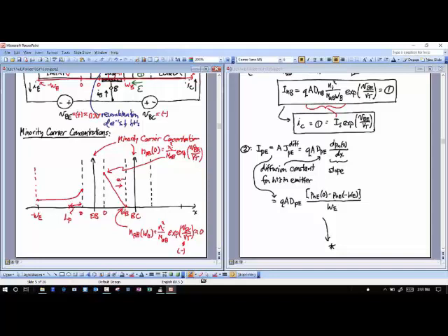That's called a diffusion length within that emitter. And that's something that you'll learn in 130, how to calculate that. It sort of approximates a straight line there, but it's not exactly the straight line you would get from that point to that. Okay? And so if I do that, then I can plug in all that same math here for the whole current in the emitter. Right? Area times the diffusion current, and that would be equal to Q times A times the diffusion constant for holes in the emitter times the slope. And it's really that slope that I want to get at there.